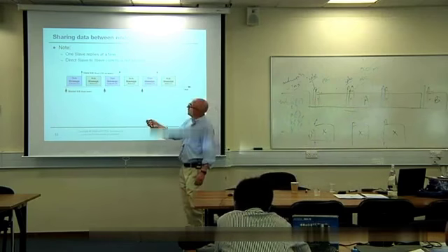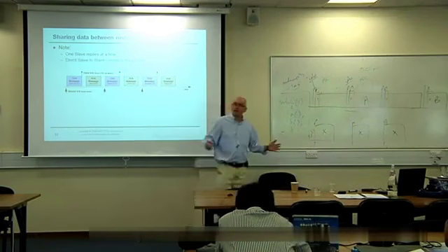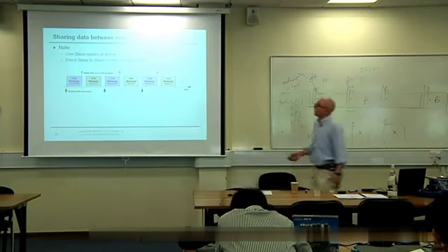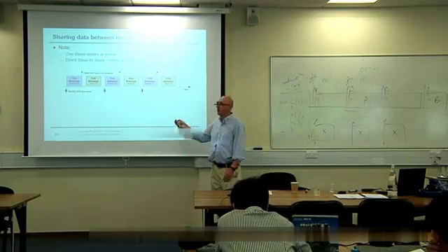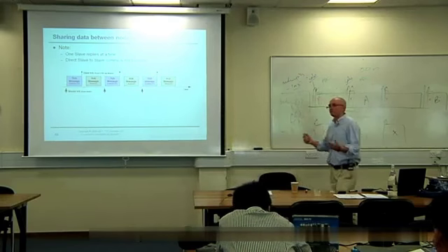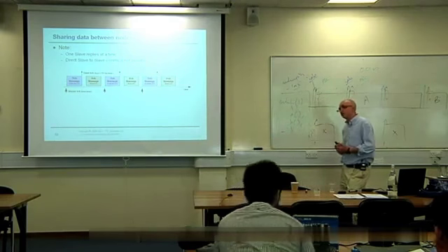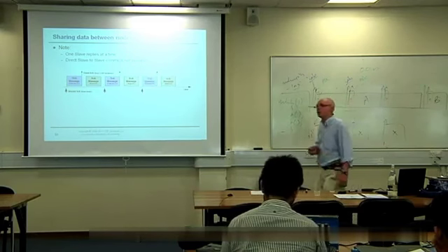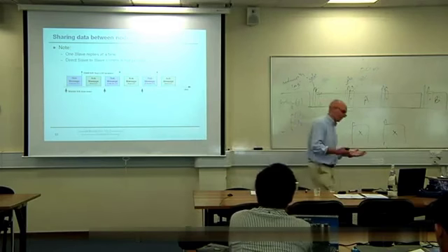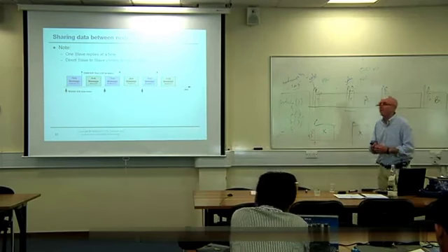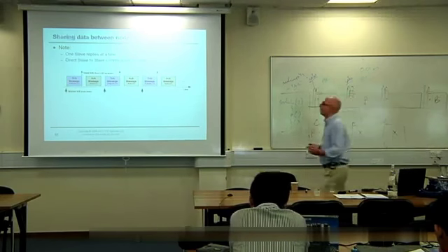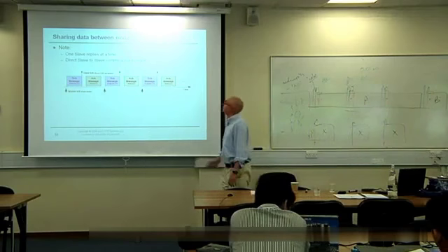So if you want to have 1 millisecond ticks in the system and a little bit of overhead, you're not going to manage to get every slave to reply in a typical environment, because it would simply take too long. So there has to be some kind of compromise between the tick length and the message duration, and there's nothing we can do about that. There's a basic limitation depending on the baud rate of the bus we're using as to how fast we can transfer the data.